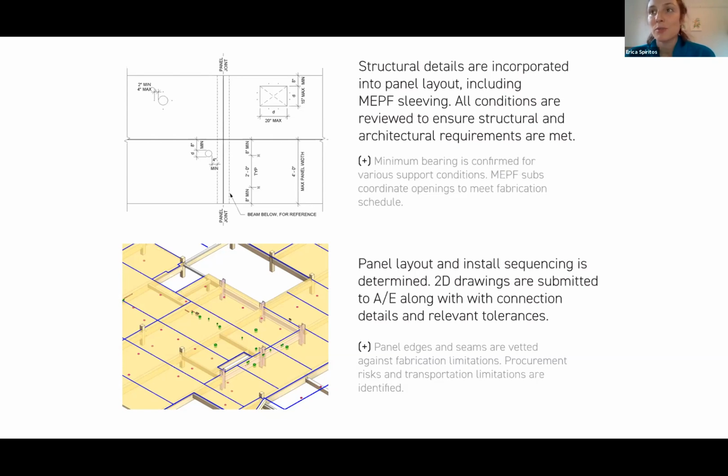And that's what enables the prefabrication of the timber structure, and then enables speedy construction, not just in the timber erection, but with all the follow-on work that happens in the installation of fire sprinkler pipe and plumbing and electrical hardware and things like that. So it's a lot of work up front to coordinate those trades, but it's definitely worthwhile. And we find that there are really significant benefits in terms of quality of work, schedule enhancement, safety of work on site, and then just cost reduction because of that reduced construction timeline.